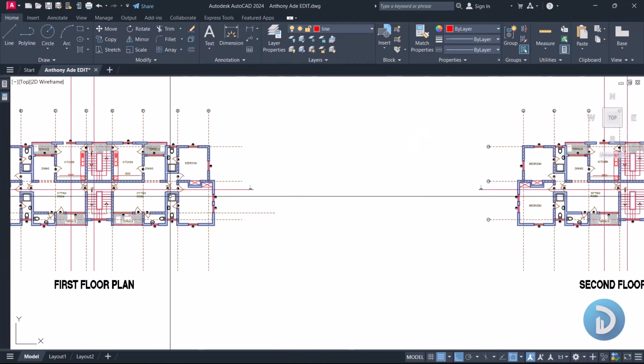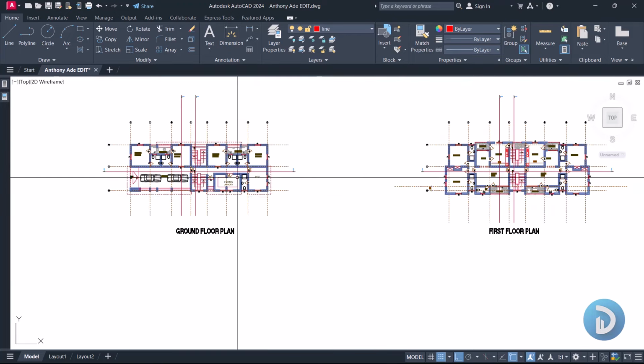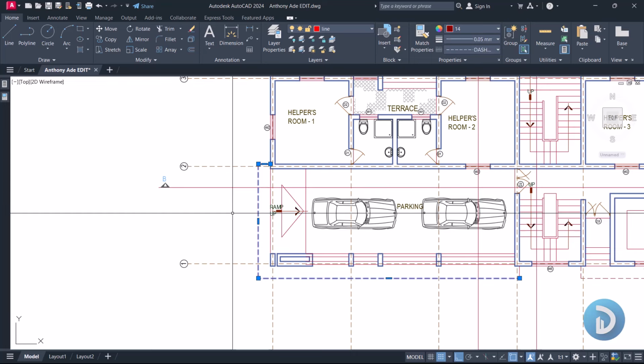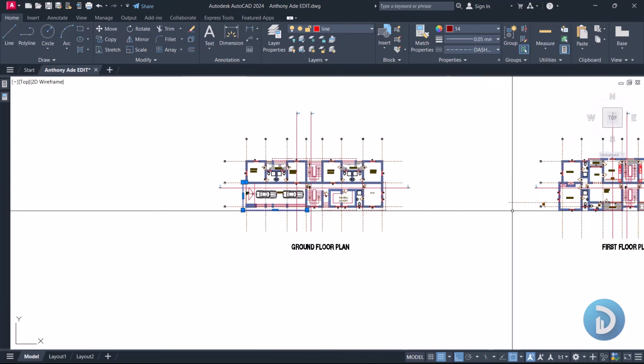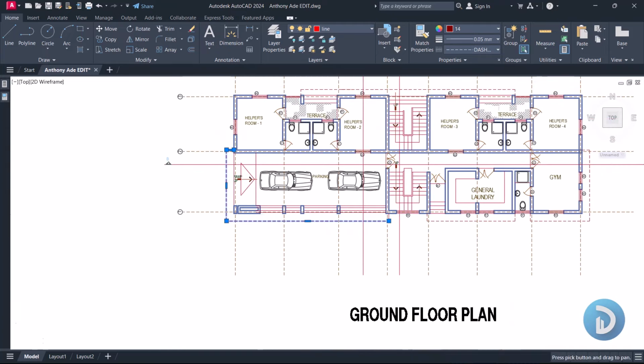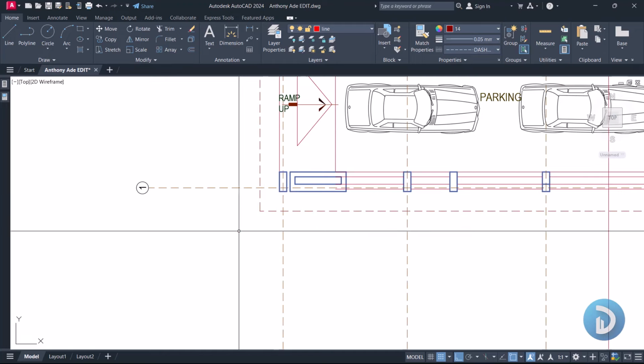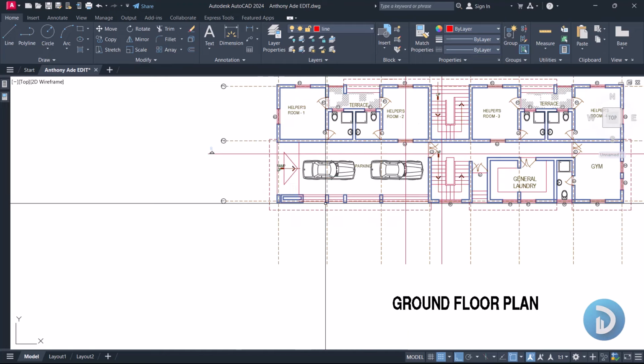Okay, and if we come back to our ground floor plan, there is an indication that we have a cantilever when we move from this ground floor to the next suspended floor. Okay, so this broken line over here denotes we have a cantilever.